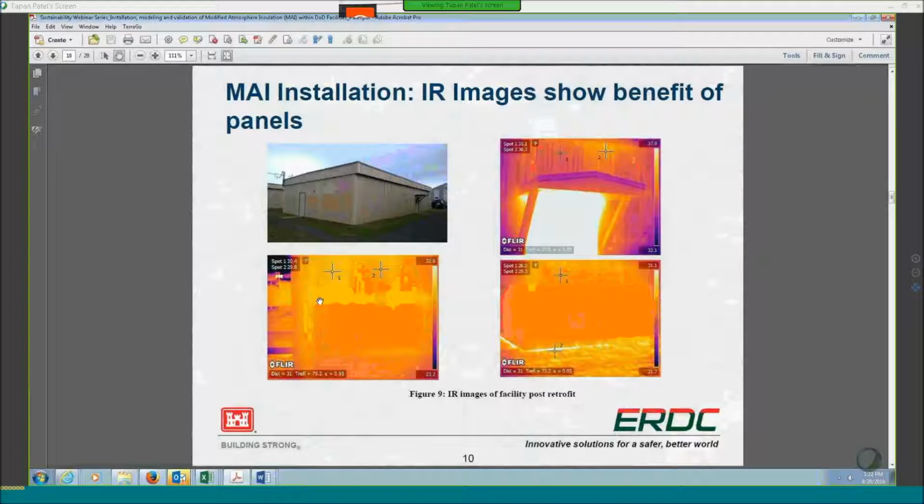Incidentally, you can also see where we had put in our polyiso here. These are some of the yellow strips right here. These are where the fasteners went, and you can see that pretty clearly. So that's one of the important lessons we learned here. We weren't sure how effective this would be, but it turns out it actually works pretty well. So IR imaging is a good method, at least in this kind of facility, to validate and make sure that your panels are still intact. Ultimately, what that does is, for example, if I had lots of failed panels, that would affect my energy modeling.